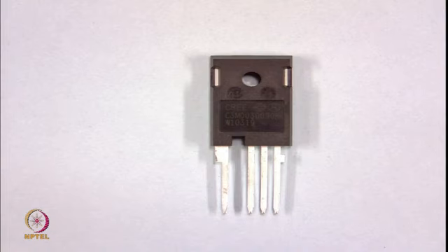So, with this we conclude the basic introduction to the power devices, where we see that silicon based IGBTs are going to dominate the market, at least at the medium voltage, medium power rating. In multi-level converters also, silicon based IGBTs are going to play the most important role, but slowly within a couple of decades many of these applications will see more and more use of silicon carbide or other wide band gap devices.